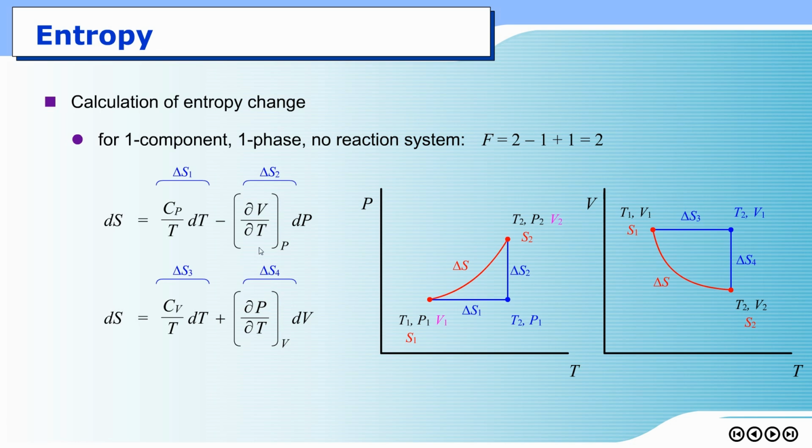So finding the differentiation of pressure will be relatively simple. On the other hand, if you try to find dV by dt using a cubic equation of state, you have to rearrange the equation of state so that you can write volume as a function of pressure and differentiate it subsequently, which will be more complicated. On the other hand, if you pick a simple equation like the Pitzer equation of state that can be represented in terms of volume equal to something, then you can take that differentiation right away without concerning how difficult the differentiation would be. So again, it depends on the data that you have on your hand.